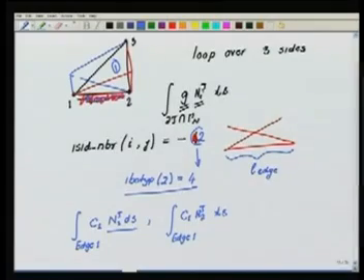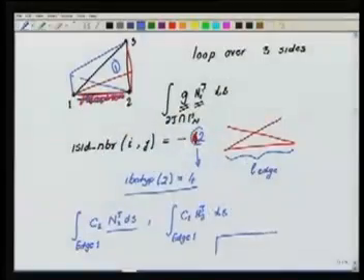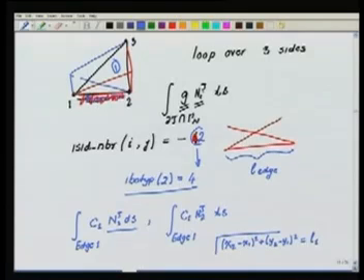Okay, so I'll have to find the length of the edge. How do I find the length of the edge? Length of the edge is very simple. It is essentially the square root of (x2 minus x1) squared plus (y2 minus y1) squared, if I take the first edge. This is equal to L1. Similarly, I can find the length of all the edges of the element.